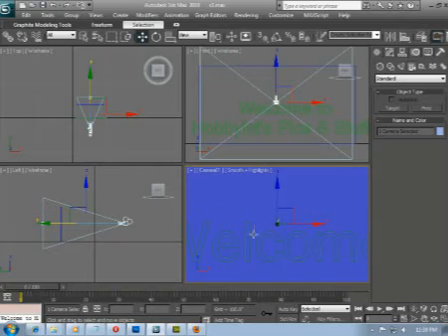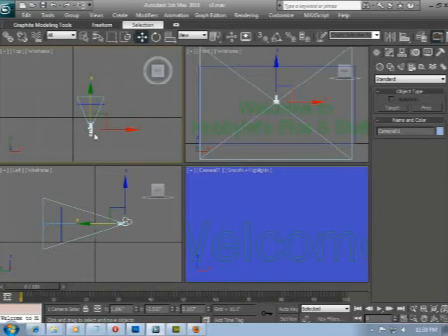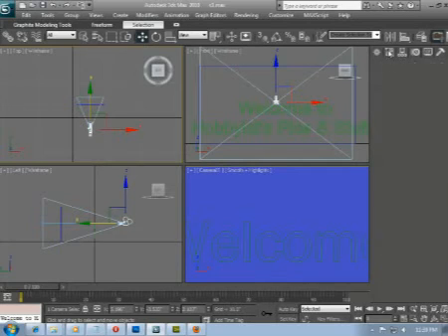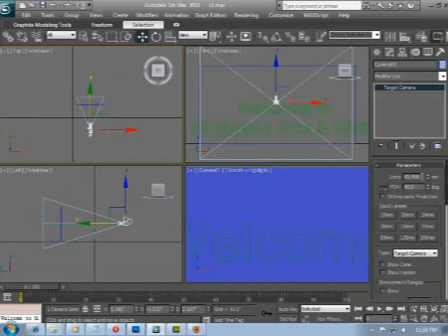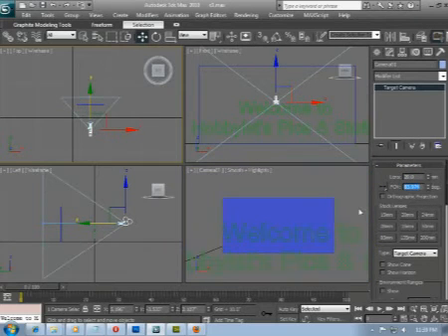Let's right click in the top view. Let's select the camera, but before we move it, let's double check what lens length we're using. That's the Modify tab in the Parameters section, and we see the default 43.456. That's actually the human eye value. So since lens length is the enemy of depth perception, and we want depth in our text, let's take this right down to, say, 20.